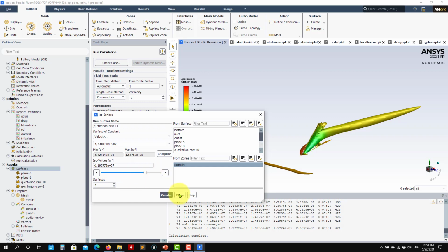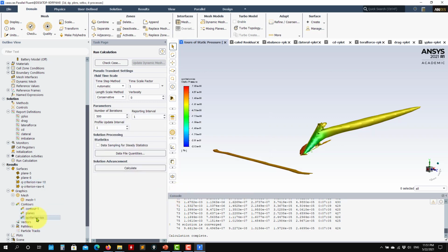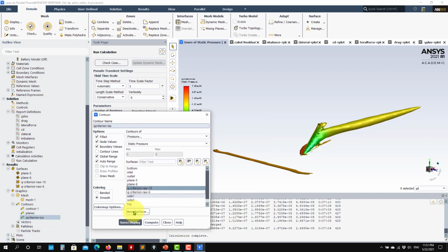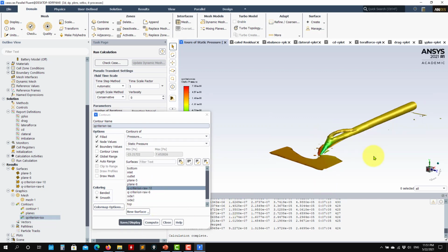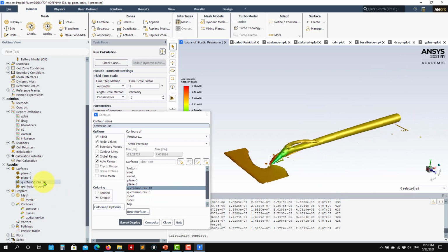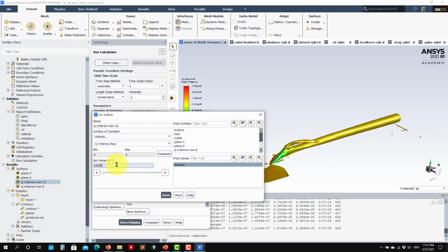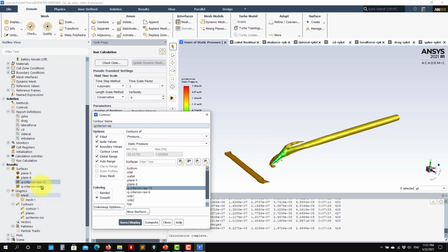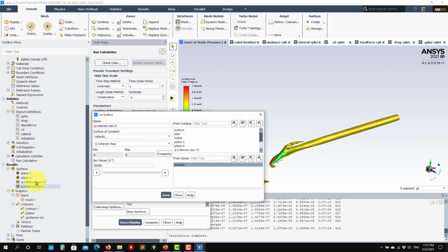The thing is that to capture the vortex, the Q criterion is a positive value. Sometimes it's tricky to find the right value. So usually I start with something like 1000 and then I start to adjust that value. So let's see 1000 and getting this. It's capturing too many structures. So let me put it like this. Let me recall what I put here, 50,000. Okay, so let's go 50,000.